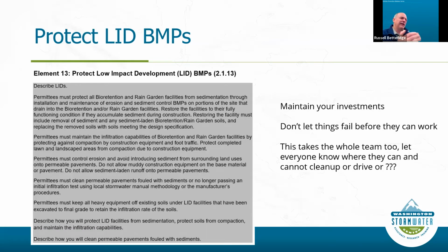Protecting the LID. This is kind of that out of order thing because you really need to plan on protecting your LIDs right from the beginning. If you've got a rain garden, if you've got infiltration areas, you need to be thinking about that in your site planning right up front. How are trucks going to get to the site if they can't drive over that portion of the parking lot because it's going to be pervious later? Really look at that LID and maintain that plan and that investment. Maintain that. Don't let it fail before you even build it.